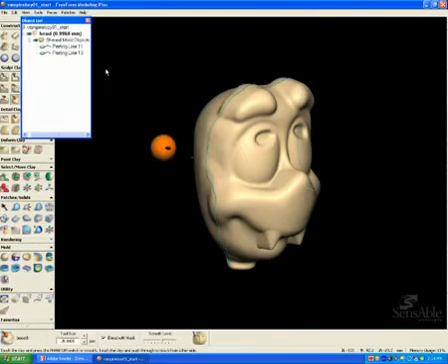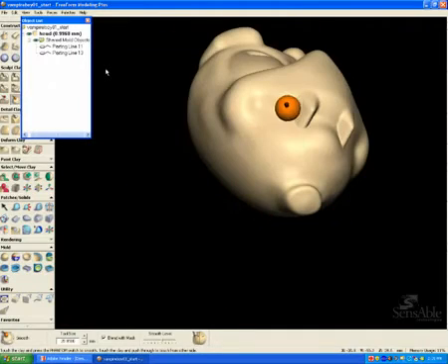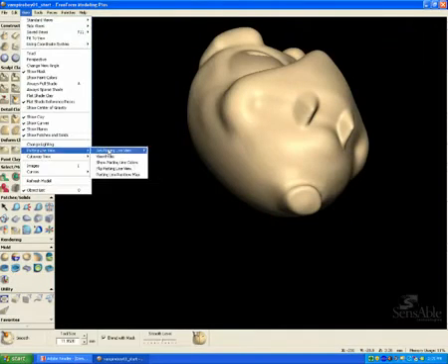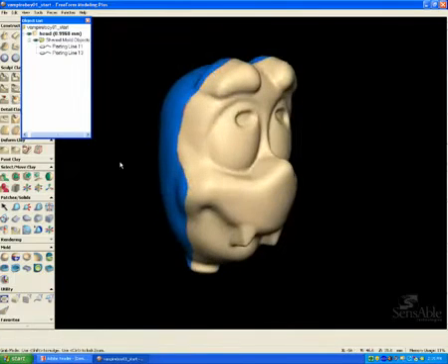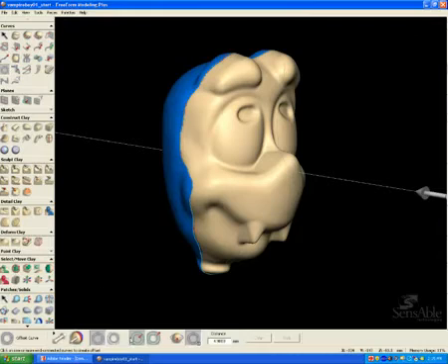And right there I'm using the fixed draft, giving it an angle so that when the model is actually created into a mold, there won't be any issues with the draft, and it will come out of the mold nice and easy. So I'm just going around with my smooth tool to smooth out some areas around the parting edge so that it is nice and transitioned.